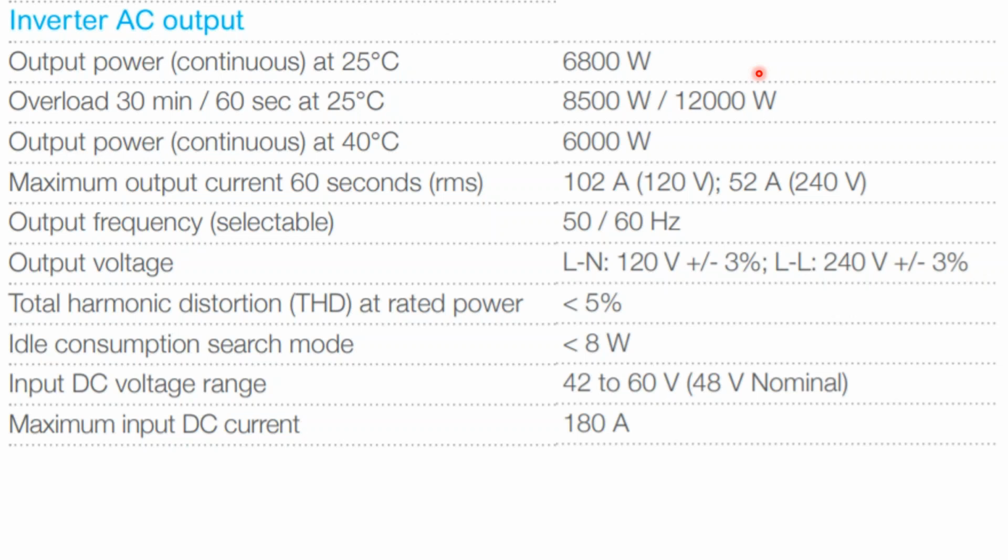Well, if it were to get up to 14 kW for a half an hour, this system could actually deliver 17 kW for a half an hour. And so this system is well sized to accommodate our air conditioning loads, and it can even burst up to 24 kW under 60 seconds. So it can handle some level of inductive heating and cooling and variable loads.